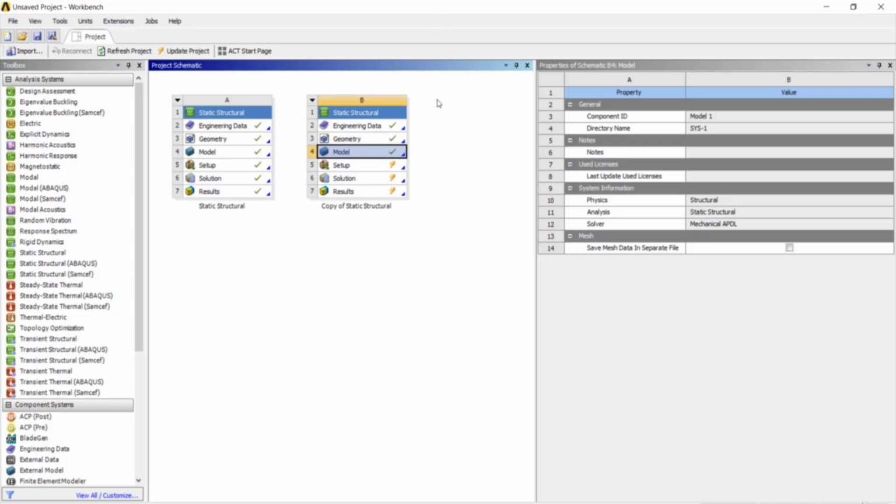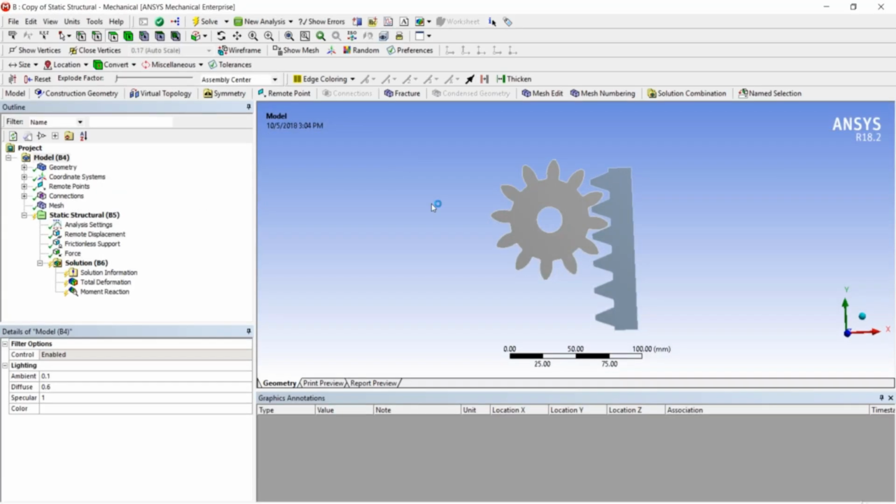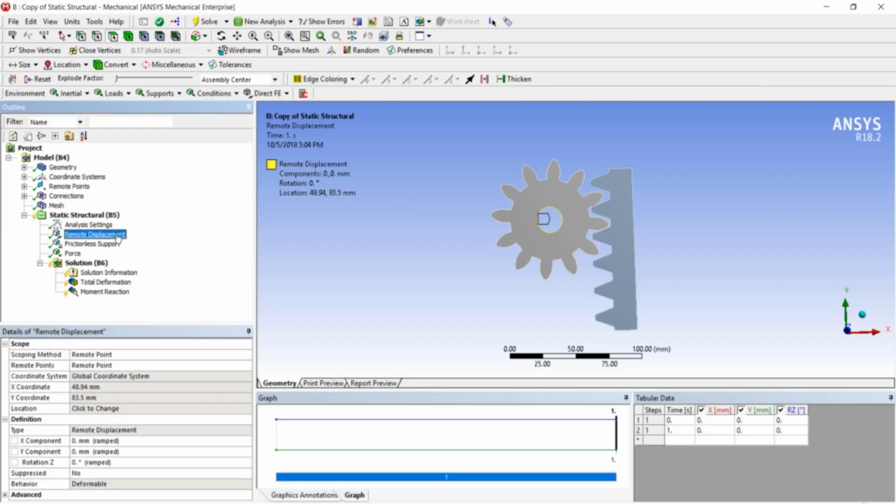Likewise, it is going to be represented in the alphabetical order here. So I can just double click on the model cell so that it maximizes again. After opening ANSYS Mechanical once again, here we need to change some boundary conditions before we recalculate the total problem. The first condition is you need to select this remote displacement, and here you need to